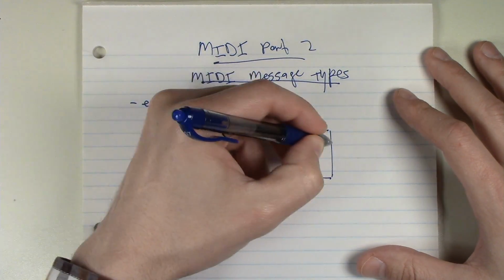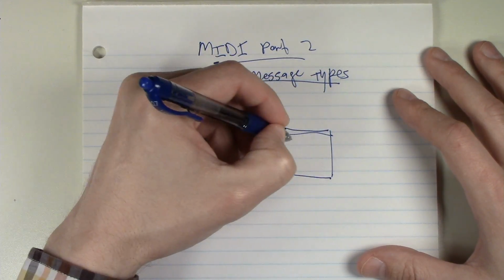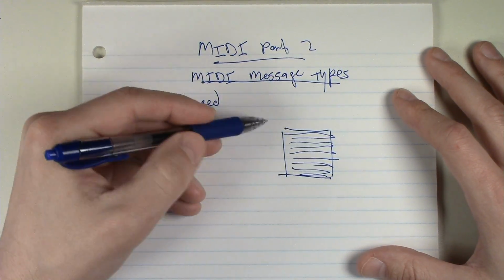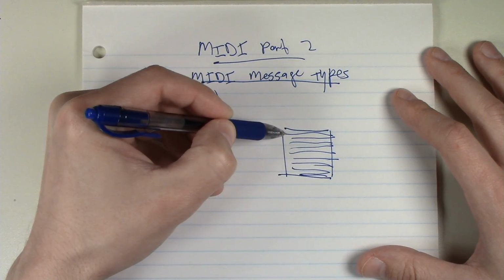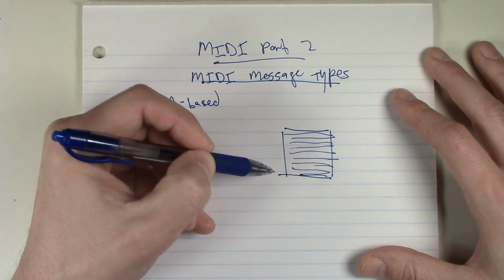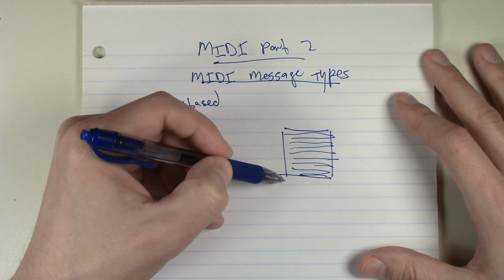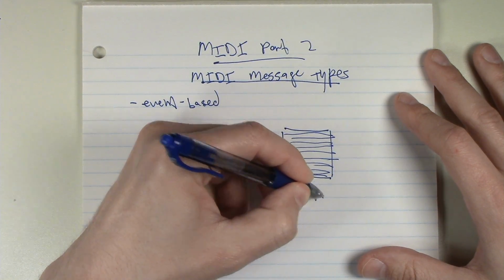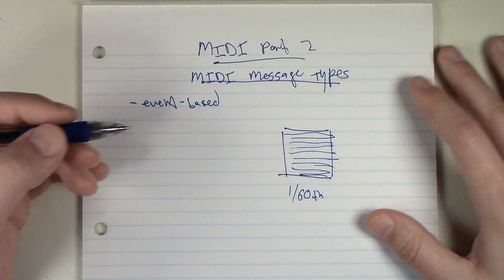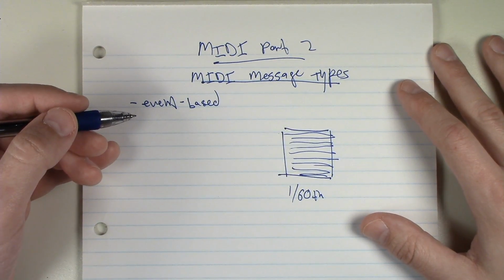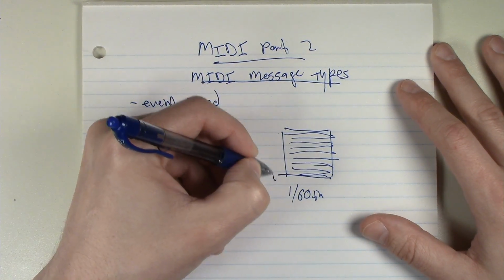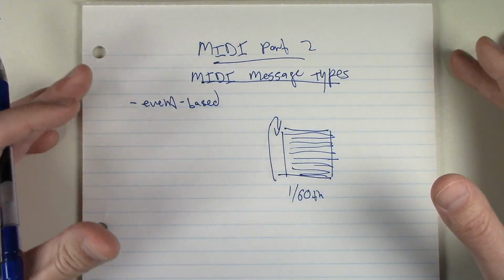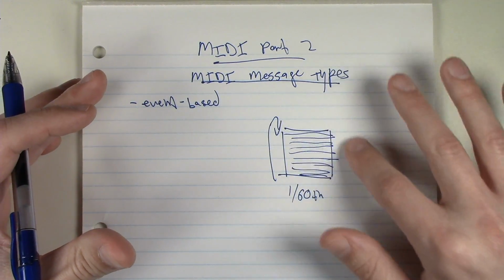We've got pixels going across the screen. These are lines of pixels usually. And normally, the video signal sends each line one at a time from left to right and then from top to bottom of the screen. And then when it gets to the bottom of the screen, let's say that's 1/60th of a second, if we're talking about 60p type of a video signal, it goes right back up to the top and starts all over again. So if there's nothing changing on the screen, this process is still happening.